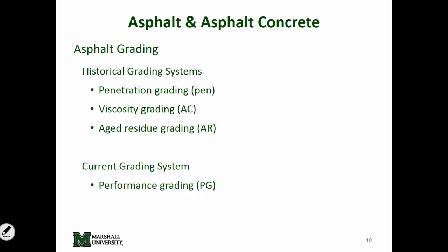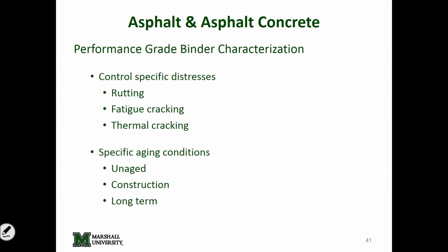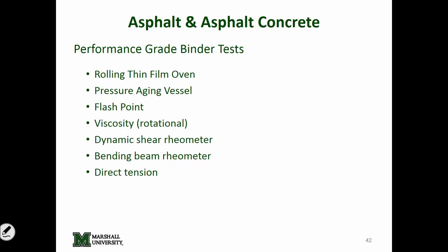Grading systems. I haven't seen anything on grading on any of the example exams I've seen, but it's in here because I had it in the class. When we look at how we rate materials nowadays in the asphalt world, it's on performance. It used to be we just had a set of properties and we tried to emulate those, and we felt that those gave us good results in the field. Nowadays we're going back and looking at the specific behaviors we want to see, rating the asphalts based on that and designing based on that. So it's about performance these days, not about the design properties we thought were the right properties.